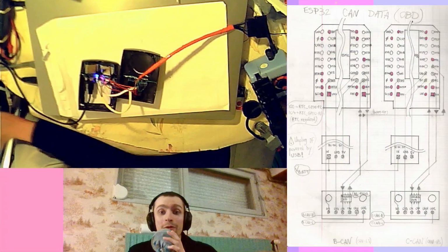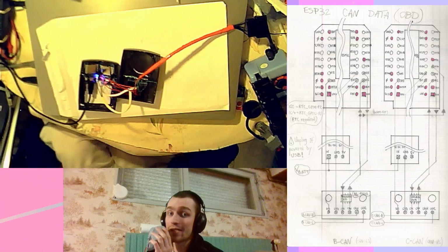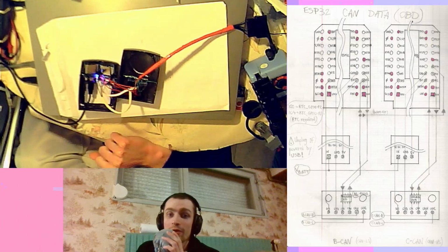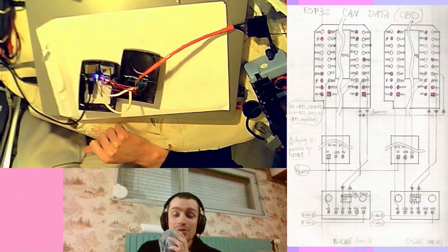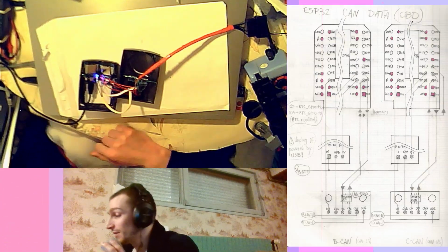I think it should blink, or just have a lower brightness, because you won't really see the bits. The mean applied power will drop slightly, and you should see a brightness drop when there is CAN bus data on the bus.